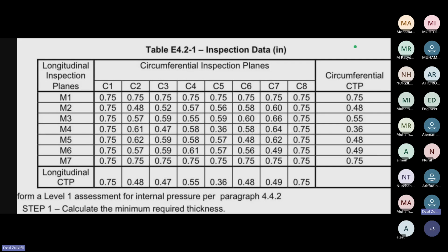So what this means is that when we do thickness measurement for FFS, we want to take the thickness such that we cover up until where the thickness is acceptable. Okay. And the definition of acceptable is that it is close to nominal thickness. Basically, we want to scope out the thickness measurement until the areas where they are okay, where the thickness is more or less the same as original, there is no damage, so that you can completely capture the scope of the damage.